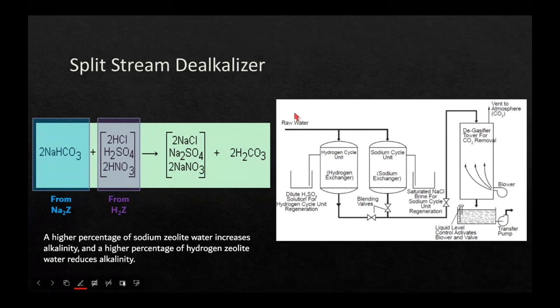And will be red. So raw water is going to have stuff in it like magnesium chloride, which is permanent hardness, and it's going to have calcium chloride, and it's going to have calcium bicarbonate, and it's going to have magnesium bicarbonate.